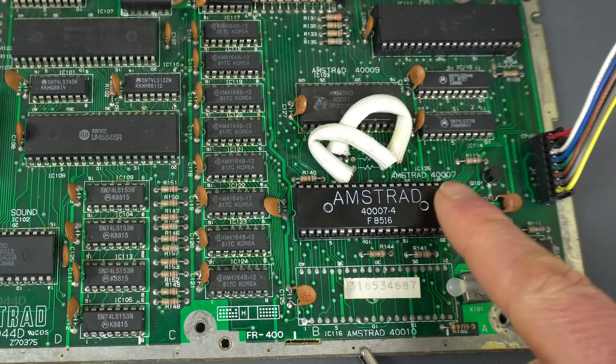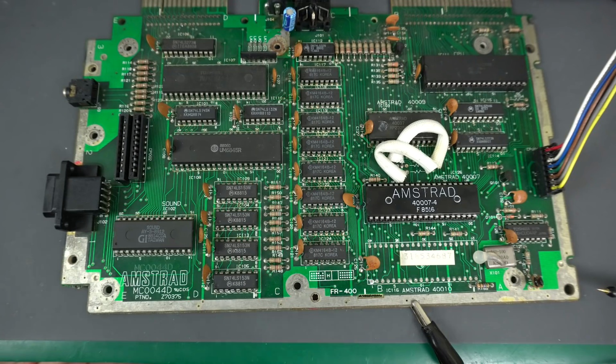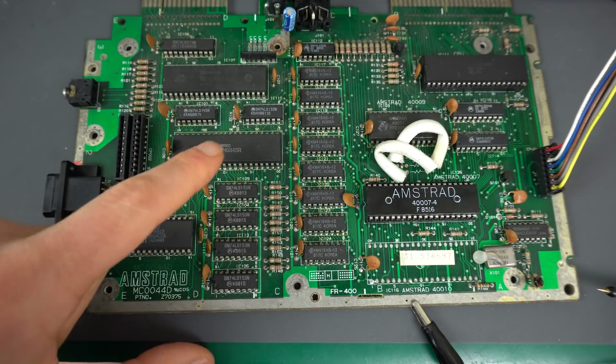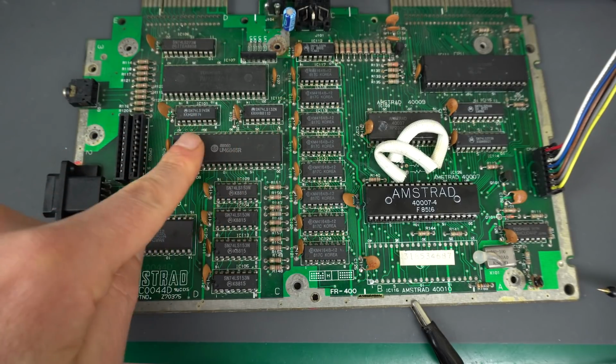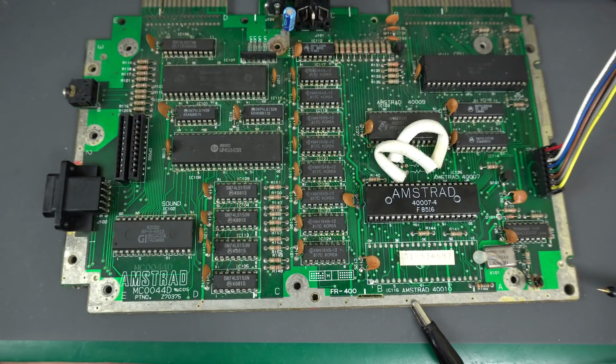Then it's likely that the gate array is fine, which is good. It's the most expensive chip on the whole board. And the fact that we're getting really weird frequencies from the CRT controller, but we're actually feeding it correctly a 1 megahertz signal, that tells me that there's something wrong going on in there. So I think I'm just going to pop it out and try a new one instead.